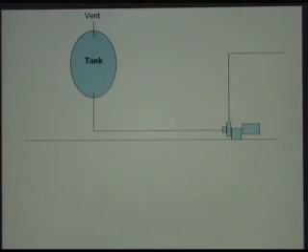Let's say we've got a tank, above grade, sitting several feet above a pump. We're taking fluid out of the tank, into the pump, and it's being pumped someplace else. The fact that this tank is physically over the inlet nozzle to the pump means that the fluid will gravity feed straight into the pump. That's known as a self-priming system. All pumps will operate this way. That's the way we like to see them. Can't get them that way all the time, though.